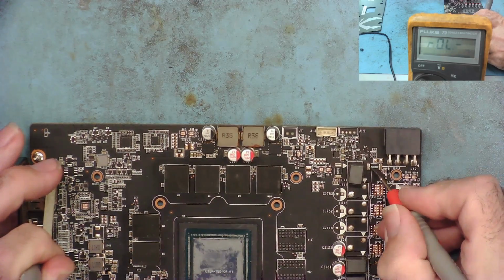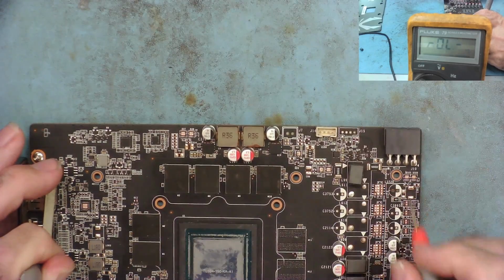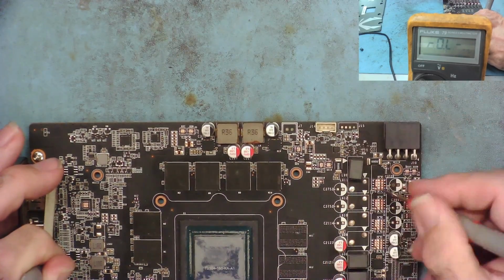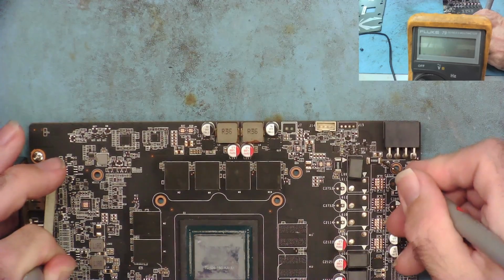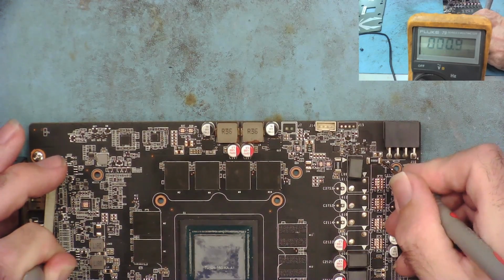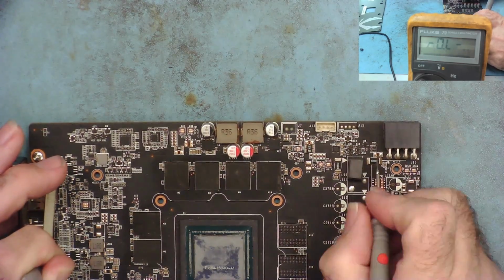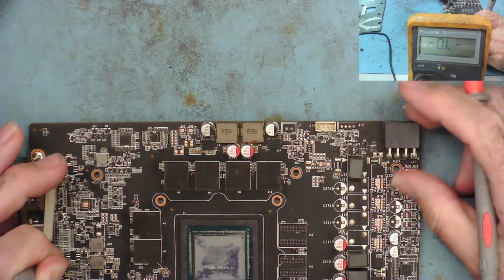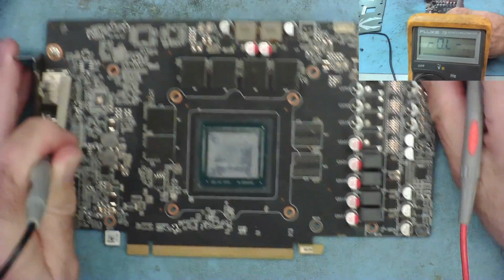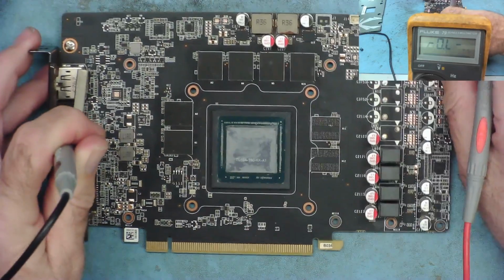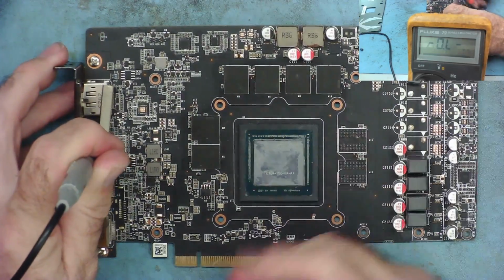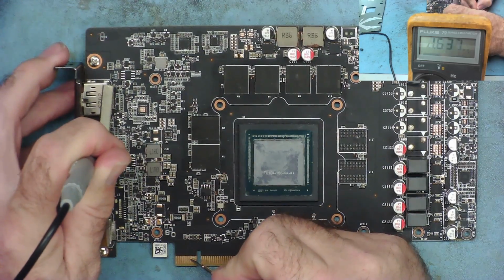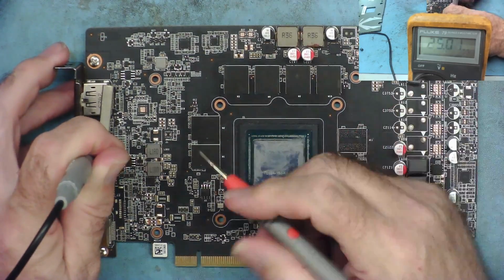Oh, that looks like we have a short. Yes, we have a short on 12 volts. Do you see it on this current sense resistor here? So somewhere on here we have a shorted high side MOSFET. That's the first thing we have. That probably explains that increasing reading I was getting. So let's see if we can find out where that actually is. I'll just check the 3.3 volts as well, which is the fourth finger in. That's okay, no short there.